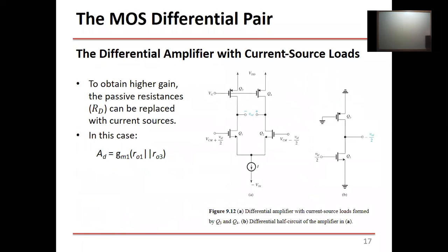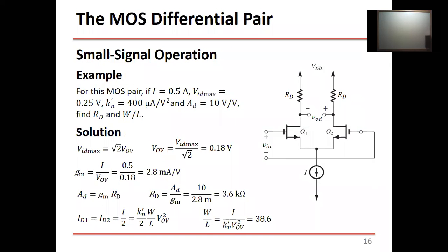Okay, so in designing or fabricating ICs, we always try to avoid resistances and large capacitances. As I mentioned before, maybe in the current source chapter, we try to avoid building resistors. Instead, we replace these resistors with a current source. Designing a current source with a transistor is much easier and much preferable than implementing a resistor.